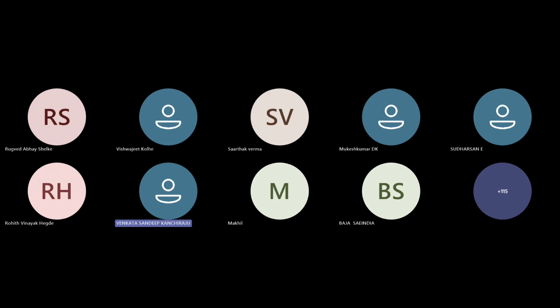Is it necessary to use the SKC file? There is no requirement that you have to use this file only in this session. You can use linear 2DOF, linear 2DOF1. From your perspective, the SKC file will give you a more accurate projection of your suspension compared to the linear 2DOF and 1.